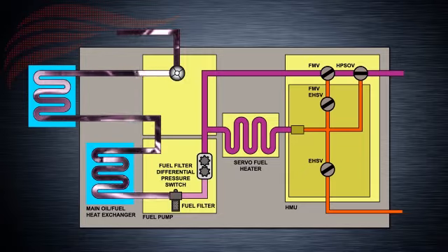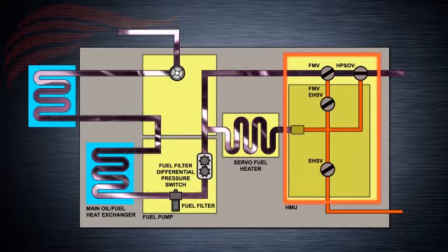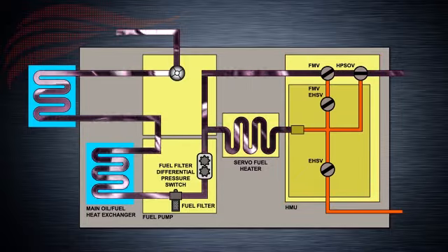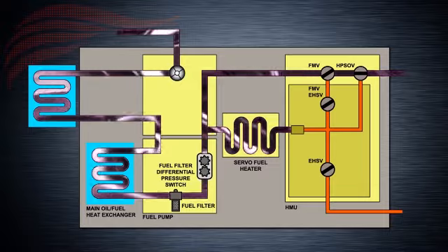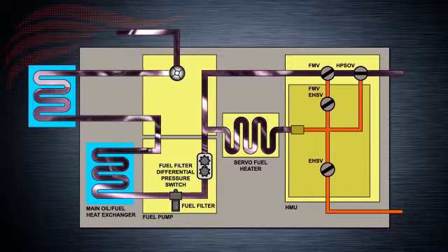Following all the components we've discussed, fuel finally goes through a hydromechanical unit. The HMU will not be covered in this lesson as it's discussed in the fuel system lesson. However, inside the HMU, fuel is metered and fuel flow is controlled by an electronic engine control, or EEC.